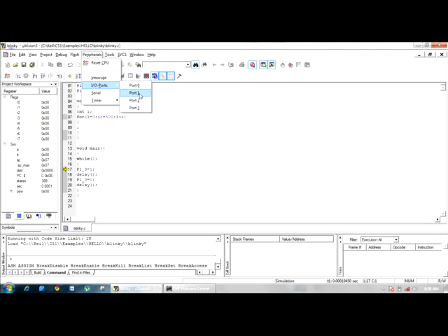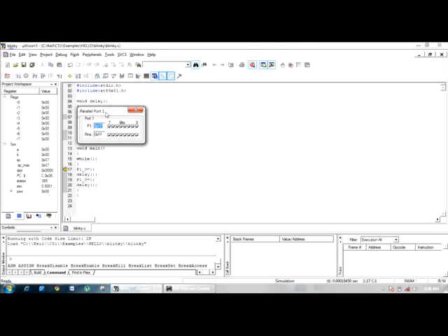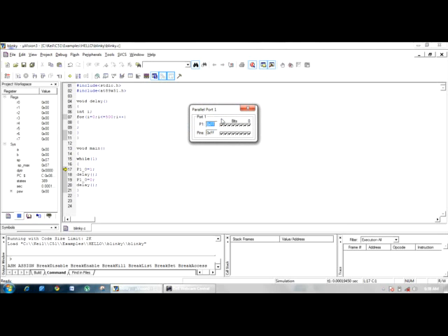So click on port 1. You can see a very beautiful appearance of all the 8 bits clearly indicated from MSB to LSB, that is bit 0 to bit 7. Initially all the ports are configured as output ports sending FF, that is all the bits high. This is the basic status of an unprogrammed 8051 chip as per its standards are concerned. So now we are going to run the program and see what is its output.